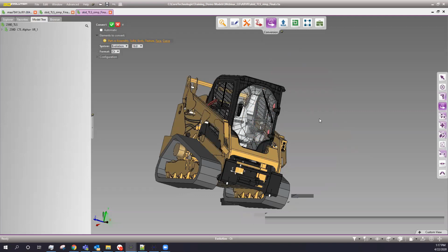They can utilize 3D Evolution or 3D Analyzer, or we can put it back into the native CAD package itself as a simplified representation, so they can see the resulting file size and don't have to worry about the lag, because that 1.6 gigabyte file is extremely slow and hard to use on the majority of engineering computers.